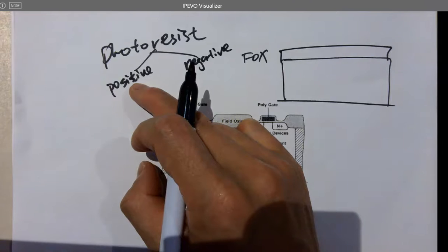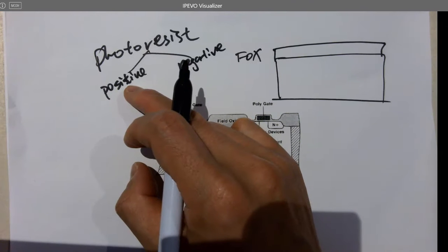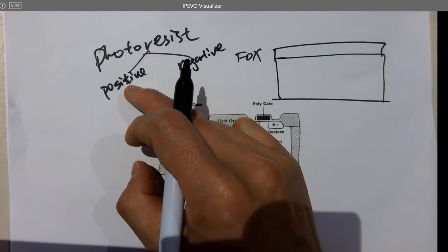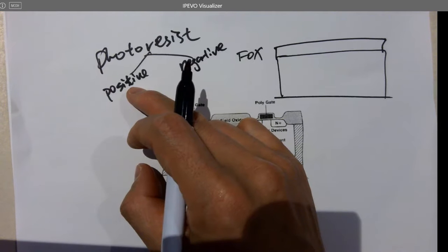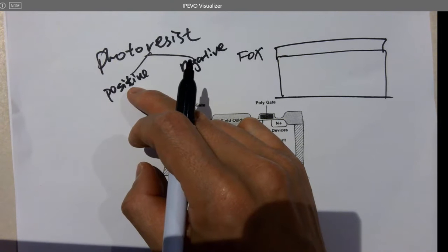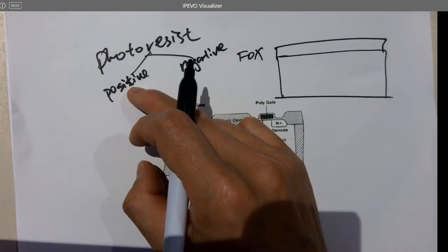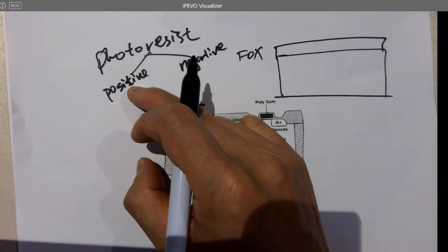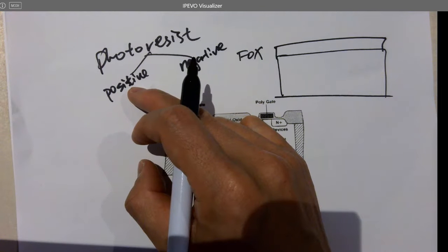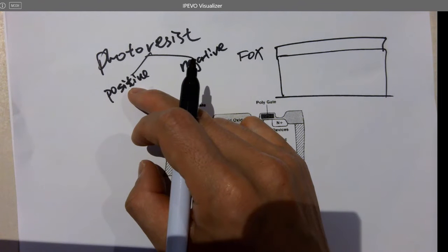So the texture of the photoresist is like a honey texture. So you can buy bottles of photoresist. They are super expensive, like 500 ml, it's usually $1,000. So you place that wafer on the vacuum. The spin coater has a vacuum at the bottom. The chuck can hold it. Make sure it's in the middle, and then pour that photoresist in the middle, like a puddle in the middle of the wafer, and turn on the spin coater.